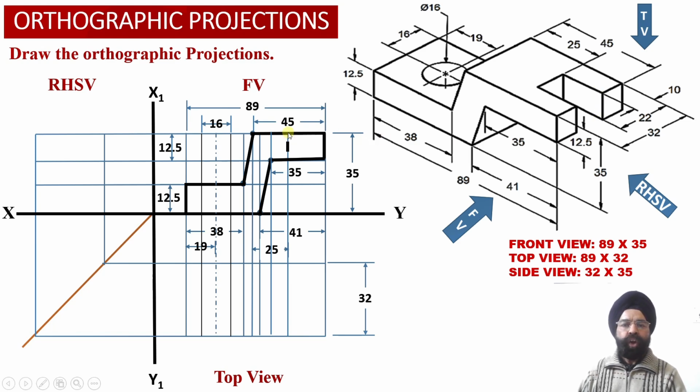So we can check that the slot, which is once again parallel to the vertical plane, has its true shape projections, measuring 20 millimeter width and 12.5 millimeter height, obtained into the front view projections. Since this surface is not visible to the observer from the front view orientation, we are going to obtain hidden line projections corresponding to this vertical surface of the rectangular slot.